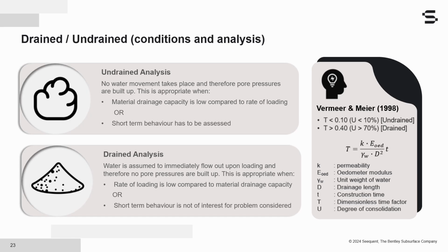So the next logical question is, what happens in between? In cases where the rate of loading falls between the limits of drained and undrained behavior, let's say that we have excess pore pressures that develop and then partially dissipate during construction, then maybe it is necessary to also include a consolidation analysis. And this tends to occur when simulating construction activities in, as we said, normally or lightly over-consolidated clays, or maybe silts, or any mixed soils with a significant clay content.